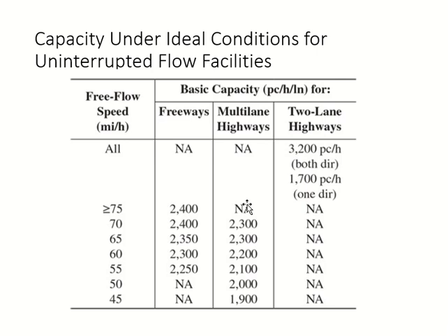Okay, one more point: why are we saying that intersections are far, so we can consider the highway as uninterrupted? Because when they are far, their effect on traffic is less. It's not like you pass one intersection and are already thinking about the next one, that I should slow down, or there are cars in front of you, or you are looking at the signal timing. The intersections are very far from each other, so you are driving irrespective of the intersection. So that's why we can consider it uninterrupted.